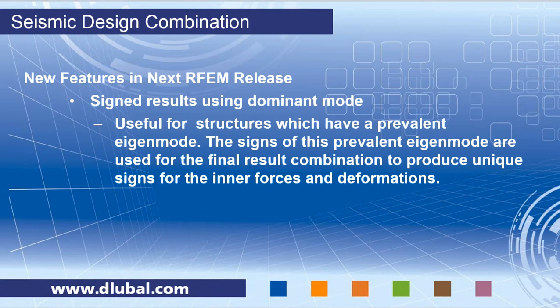You can use the SRSS rule or the CQC rule, and if you use it, you have the option to use the signs of the prevalent eigenmode and take these signs for the whole result. That means that you don't get two signs for each result combination.